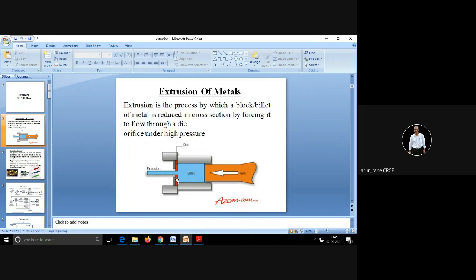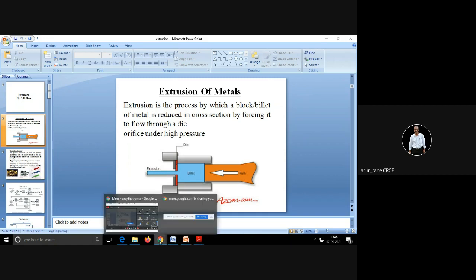Wire cut is employed when the cavities are through and through. If the cavities are blind, then you cannot go for wire cutting. You can go for EDM. But among grinding, EDM, and wire cut, wire cut is the fastest process, and it gives quite good accuracy. It depends whether it is a single cut, double cut, three cut, or four cut wire cut machine.